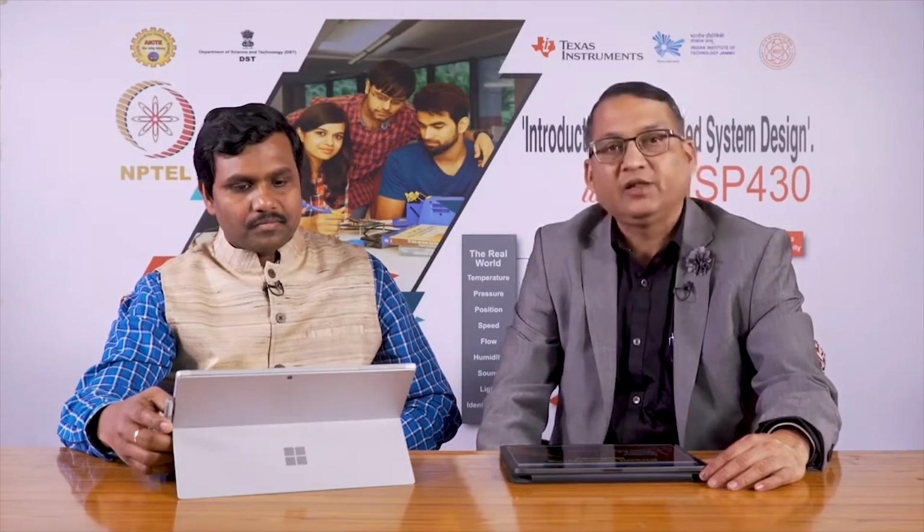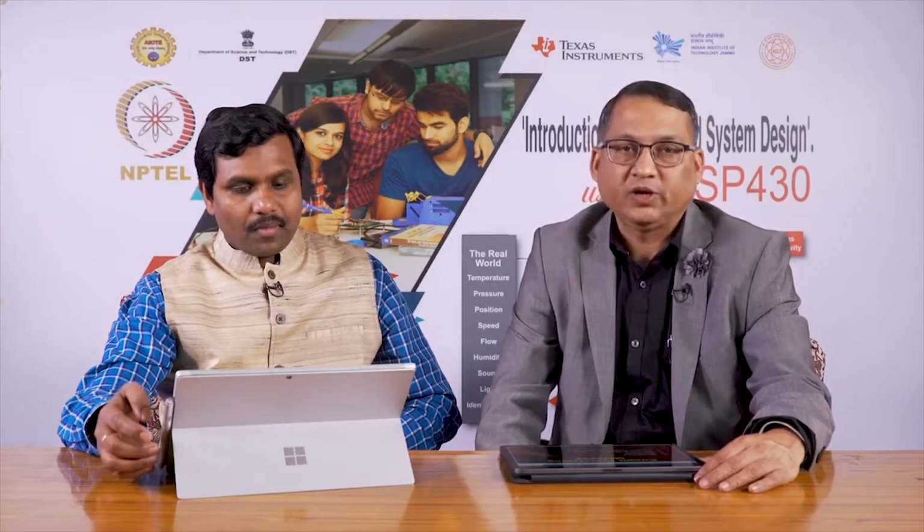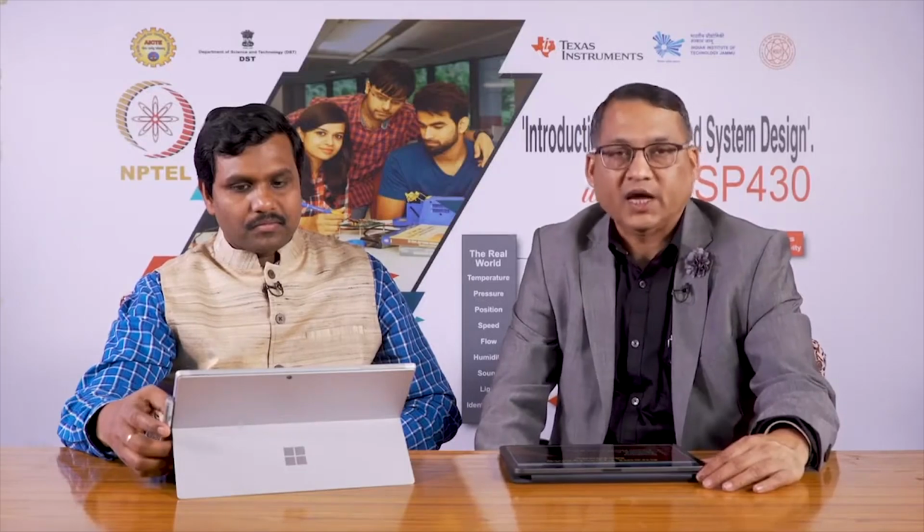Another very interesting style of circuit prototyping is what is called Manhattan style. The reason why the word Manhattan comes is because in Manhattan, New York, you have high rises, very tall buildings, and once you solder your circuit board using this technique, you will realize that with all the components rising up, it looks like a Manhattan skyline. And the fourth method, of course, is that you create your own custom printed circuit board, which takes a lot of time to design, fabricate, solder and test.